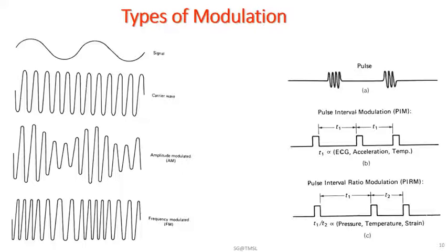At the receiver side, a multiplexed RF carrier is first demodulated to recover each of the separate subcarriers, which are then demodulated to retrieve the original physiological signals. Now, both FM-AM and FM-FM systems are used in biotelemetry, and the modulation system is selected based on the size, the complexity, the noise in transmission, and other operational problems in this type of modulation system.